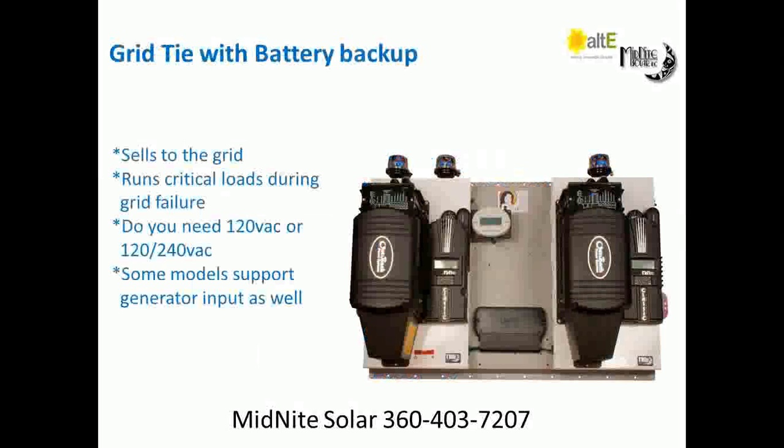Some of the other things to think about in sizing a grid tie with battery backup system. We talked about in the off-grid section, you size the inverter around the biggest load you want to run. Now let's go to a grid tie system, and that still sort of holds true. We need to ask a couple of questions. What's the biggest instantaneous load you want to start in an off-grid or grid-down scenario? And that gives us a minimum inverter size.